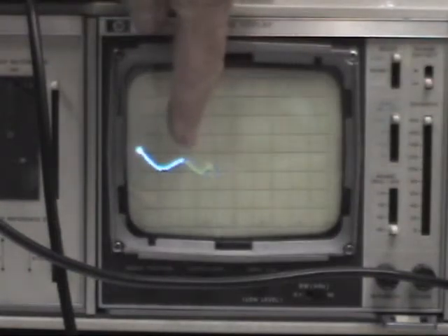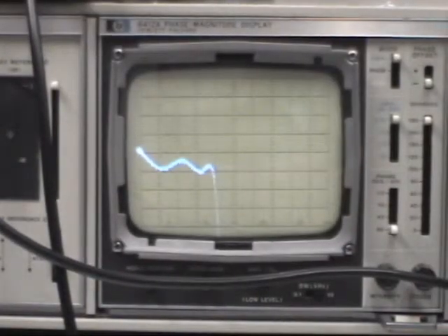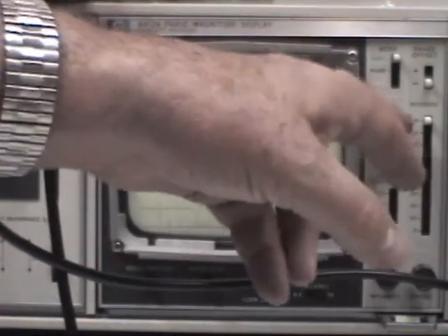We can measure the insertion loss on any one of these along the way. We're 1/4 dB per division, so we have less than a 1/4 dB insertion loss on the filter. So just moving the board, you can see, moves the cables.